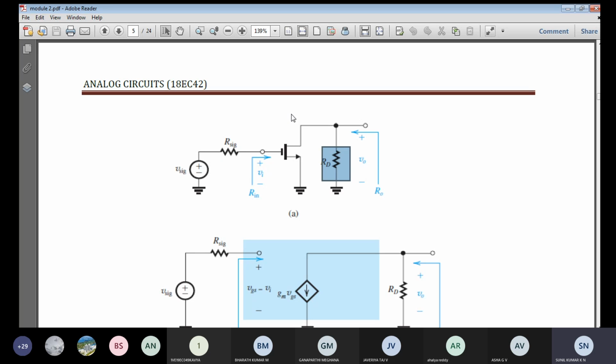Hence, in control systems and network analysis, you might have seen the Miller effect, Miller capacitance, Miller resistance, as they say. The Miller effect means whenever you have a feedback path, a connection between the output and input through any passive components like capacitors or resistance, those resistance and capacitance will have impact on both the input side as well as the output side. In that case we are going to see the Miller effect.